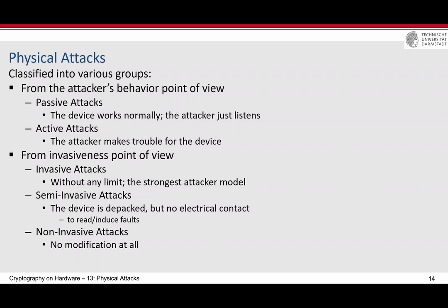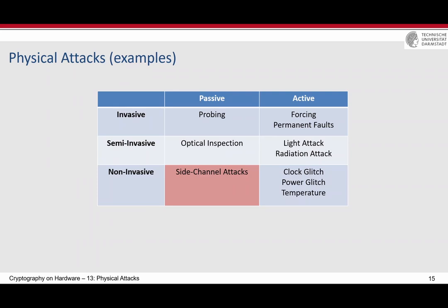At the same time, it's passive, which means that you just listen to the device, listen to its power consumption, listen to the timing which is required to perform, for example, the AES encryption. The device doesn't have any facility to understand that somebody is listening to or counting its number of clock cycles. Then protection against these attacks is the most dangerous or most difficult one.